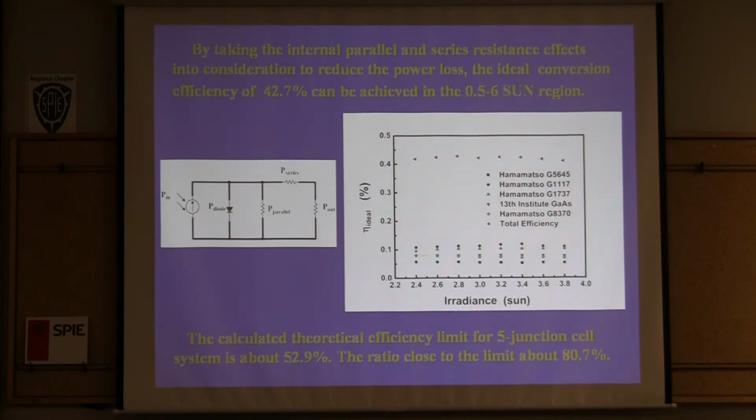The problem for the diode: this diode is not specially made for output power. It does the photon to electrical conversion, but cannot output power well because of the series resistance here. An ideal diode should have this be 0 and this be infinity. But for this diode, the curve is not very good. So part of the energy, as we analyze from the pattern, is consumed by the internal resistance.